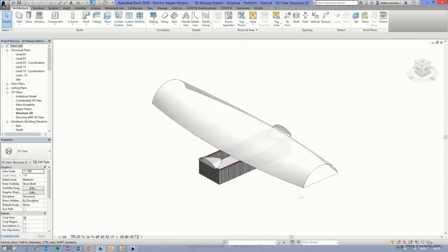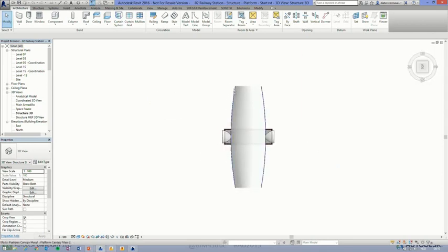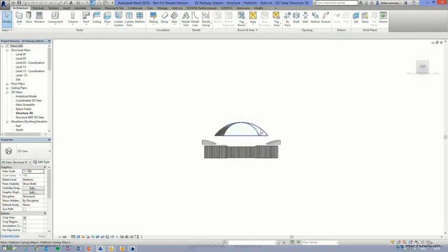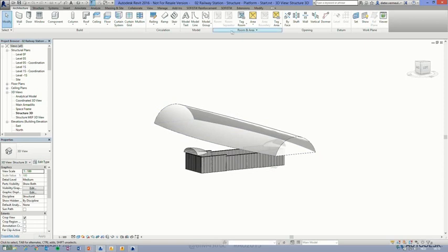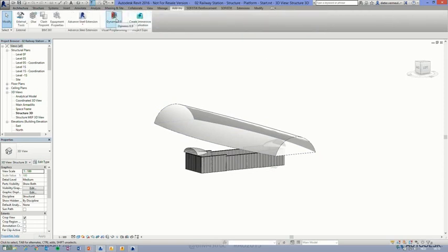Which means if you have to change your design afterwards, like saying, I started with 6 meters between each truss, I want to change it to 6.5 meters, then you have to regenerate or remodel all these trusses. So therefore we are going to use Dynamo instead to get that working better, to generate that for me, and if something changes, I will regenerate it.